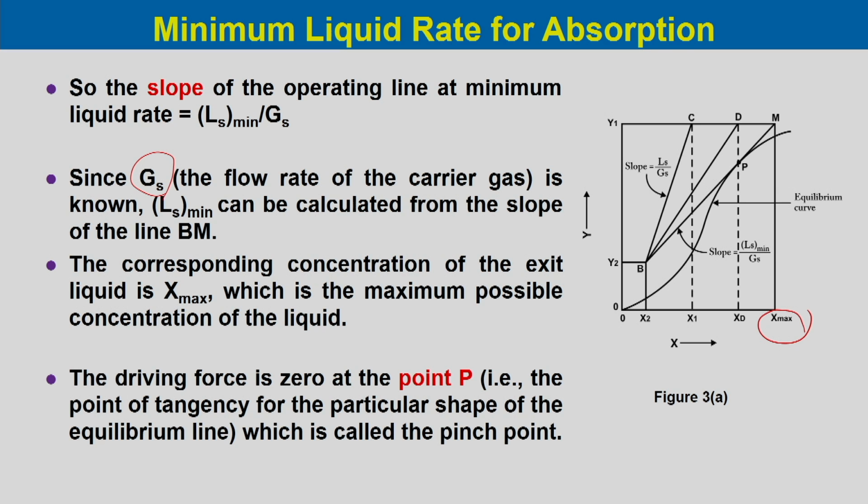The driving force is 0 at point P. So, at this point the driving force is 0, that is the point of tangency for the particular shape of the equilibrium line, which is called the pinch point. The point P over here is known as the pinch point.